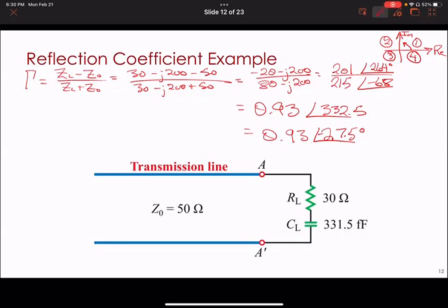You'd use a vector network analyzer. It's called a VNA. And it works based on waves, exactly like what we've been talking about. There'll be an incident wave. It knows what the incident wave it sends out is, and it measures how much gets reflected. And an antenna is an easy one to think about.